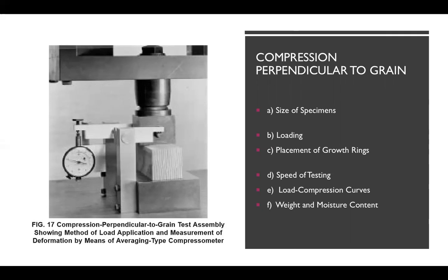And for the speed of testing, the load shall be applied continuously throughout the test at the rate of motion of the movable crosshead of 0.012 inches or 0.305 millimeter. For the load compression curves,